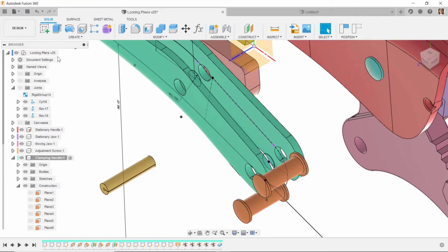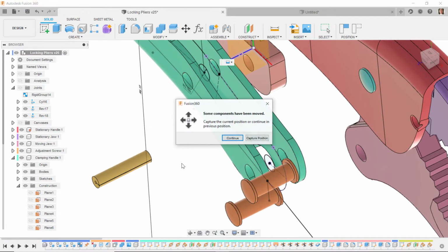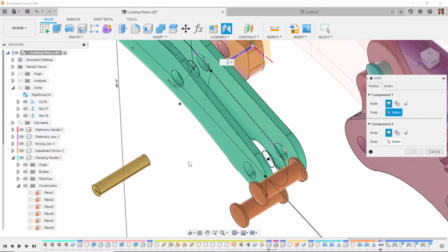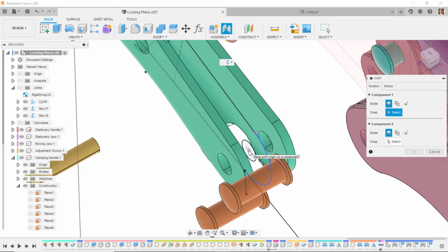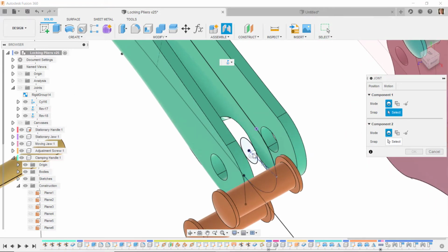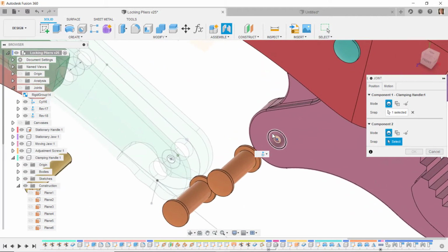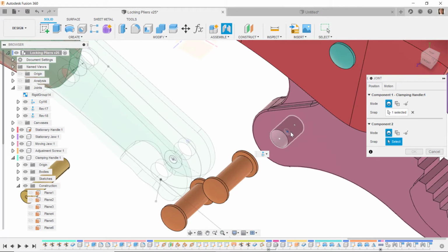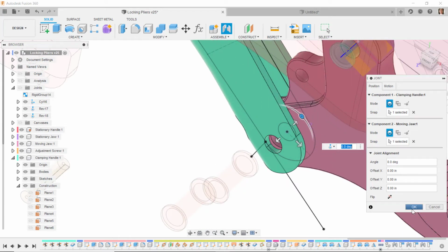So let's go back to the top level of the assembly, and then I'll do J for join, and then for the snap position I'm going to select this sketch point and pay attention to the location or orientation of that round disc. So the z-axis is perpendicular to that round disc, so I want this point selected like that, and then I will hold down the shift key or the control key, and I'll get this diamond that moves that coordinate system, and I have a revolution joint.